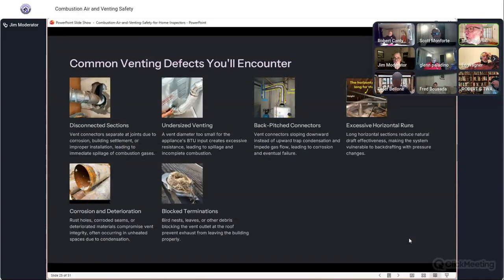But anything we burn, wood, propane, natural gas, oil, a byproduct is H2O. And we've got to get that out of the house. So I see problems in the big old three family houses with the tall chimneys not getting the proper draft all the way up and having some moisture problems in the chimney or liner problems, because maybe that condensation doesn't come all the way back to the bottom. It sits in the chimney liner and starts to deteriorate it.